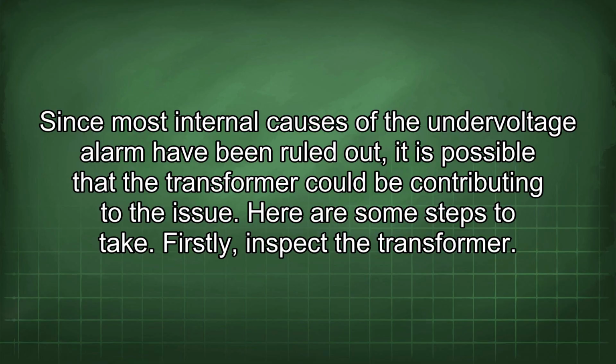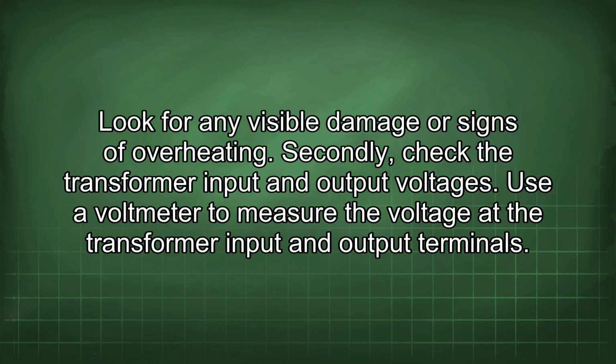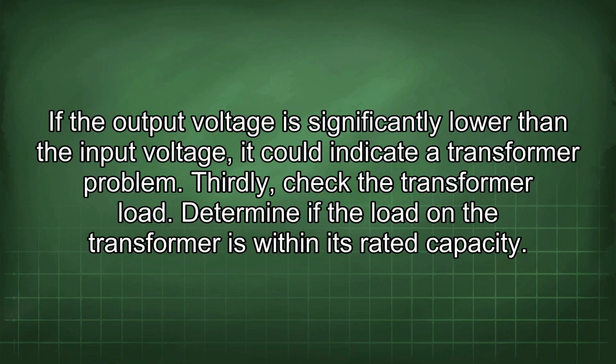Firstly, inspect the transformer. Look for any visible damage or signs of overheating. Secondly, check the transformer input and output voltages. Use a voltmeter to measure the voltage at the transformer input and output terminals. If the output voltage is significantly lower than the input voltage, it could indicate a transformer problem.